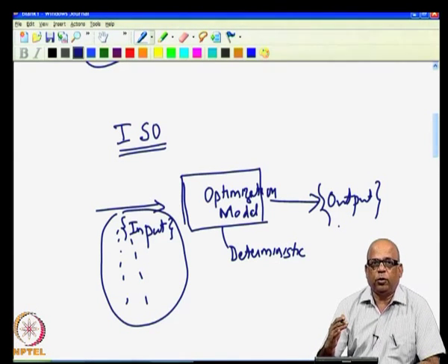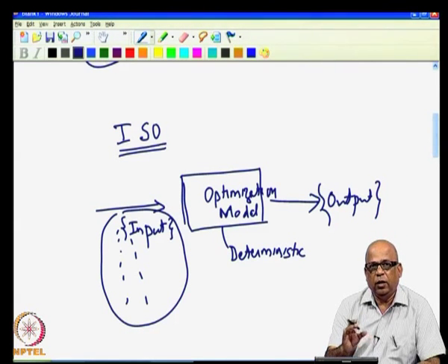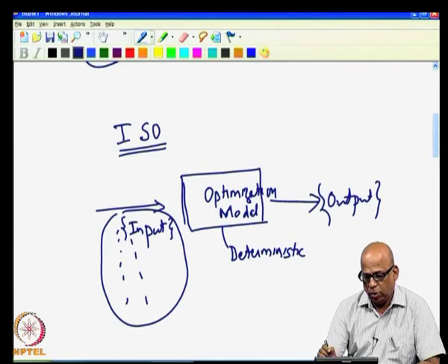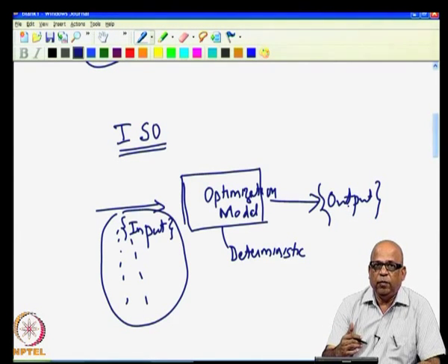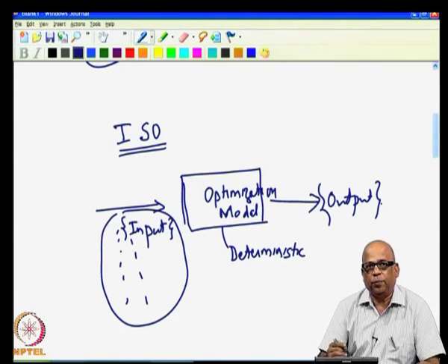Let us say you are talking about reservoir operating policy. You used yearly flows for that. So, one year flows you used and then got the operating policy. You change the sequence to make sure that the uncertainties associated with the inflows are incorporated. You change the sequence, get another year flows and then get another output, and so on.